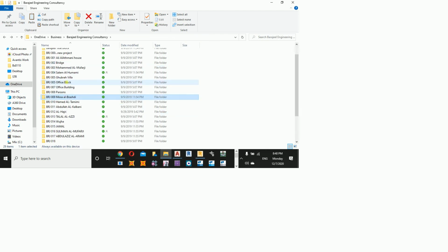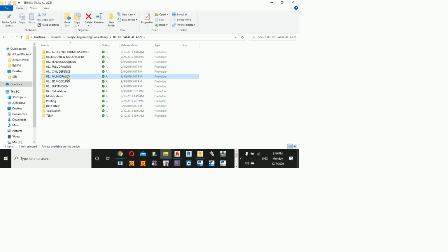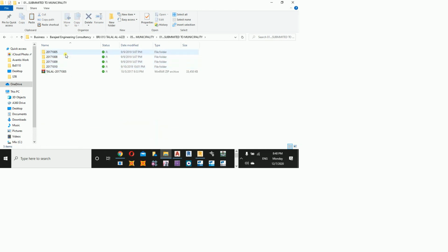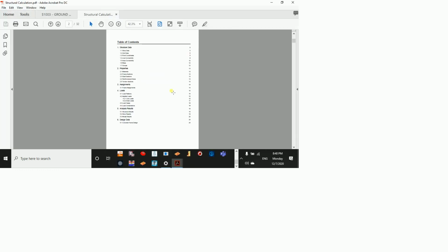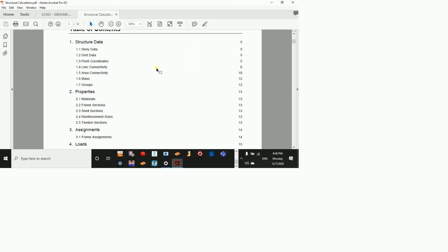The same thing. Once again, this is in ETABS, right? The heights and whatever, and you can see we have taken 1.5 as a depth. Some are going to start from minus 1.5, some are going to start from 0 and then raise it to 1.5. Both of them are fine. The base is minus 1.5 or 0. Both are fine as well.